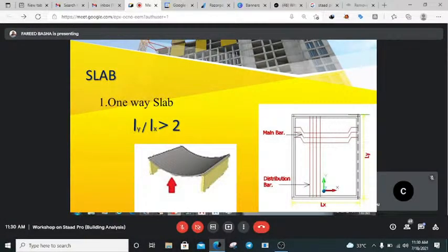So one way slab ऐसा रहता है, इसका डिफ्लेक्शन. वन वे स्लैब में हम लोग यूज ओनली main reinforcement bar in one direction and distribution bar in another direction, which is the shorter distance. We use there main reinforcement bar. So main reinforcement bar का मतलब होता है कि जो भी हम लोग बड़ा वाला like 12 mm, like 16 mm बार यूज करते हैं. स्लैब में तो मैक्सिमम 10 mm बार ही यूज करते हैं हम लोग. सो जो 10 mm बार रहेगा वो शॉर्टर डिस्टेंस में हम लोग यूज करेंगे. जो 8 mm बार होगा, मतलब जो 10 mm से कम वाला बार यूज करेंगे, वो लॉन्गर स्पैन में हम लोग यूज करेंगे इसको. सो इसमें हम लोग ये वन वे स्लैब में यूज करेंगे.